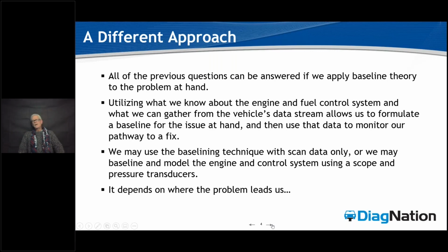So here's really the theory behind baselining: what the car should be doing when it's clean and new versus what it is doing now in front of you at your altitude. And hopefully I'm going to get back to that altitude argument here before the end of the class, because it's a very key one that makes baselining even more important for regular diagnostic approach, not just looking for deposits.